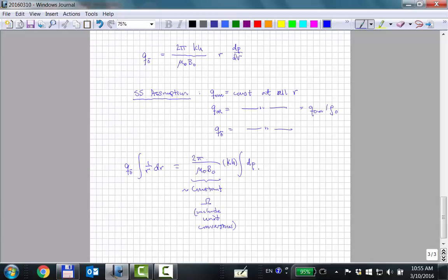Now, when we integrate this, we have to integrate it from the well bore out to the external radius, right? So from RW to RE. And the pressure at the well bore we call PWF. We already discussed that on Tuesday. It's just what we call it. We don't call it PW because the well might get shut in sometime. We have a different term for that. So we're going to call it PWF. And the pressure at the outer boundary, we call it PE, external boundary pressure.